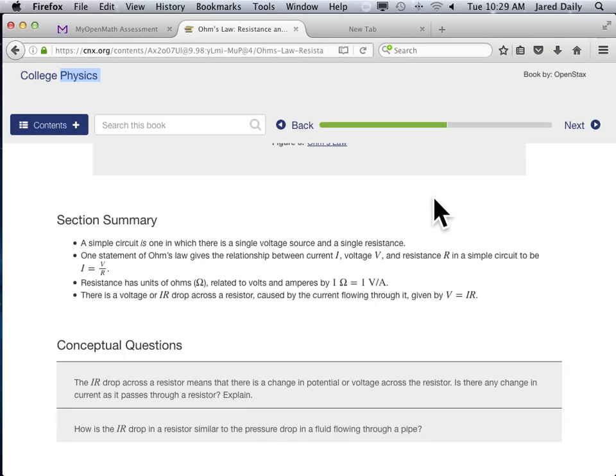so batteries are designed for specific uses because usually of their startup or their cranking voltage for vehicles usually. So bigger batteries generally have a higher cranking voltage, or a higher cranking amps rather, not voltage. So they can provide more current to start something. If you put a bigger battery in a smaller car, it's not going to hurt the car. It'll just have more than it needs, and so it won't use it all.